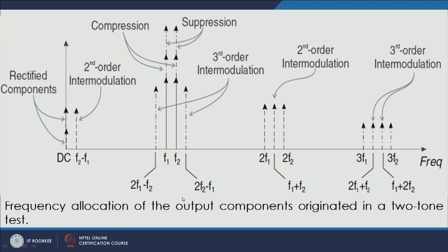So, if it is a two-tone test at f1, f2, the third order modulations, which are 2f1 minus f2 and 2f2 minus f1, are the nearest ones, and others fall much farther away, which are harmonics or the higher order intermodulation. So, whenever we are talking about intermodulation, mostly we are targeting the third order intermodulation, and C by IMD is the one for which we target. So, we have covered the parameters earlier.